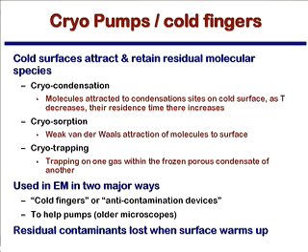Yes, sir? Is there a particular pressure range, like you mentioned each pump had an effective range? Right, so the question was, what's the effective range for doing this? Usually you only do this once you've got your sample, at the same time you're inserting your sample, and it's used to keep things down into the low 10 to the minus 7, maybe even the high 10 to the minus 8s, within the very local region to your sample. It's just using this extra cold finger to work right there after you've already got things in pretty good shape, okay?